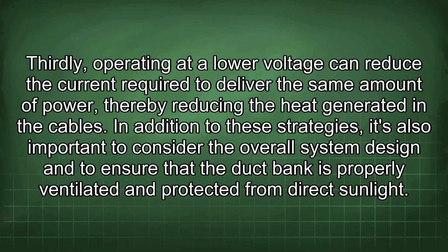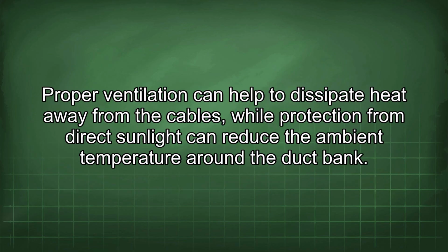In addition to these strategies, it's also important to consider the overall system design and to ensure that the duct bank is properly ventilated and protected from direct sunlight. Proper ventilation can help to dissipate heat away from the cables, while protection from direct sunlight can reduce the ambient temperature around the duct bank.